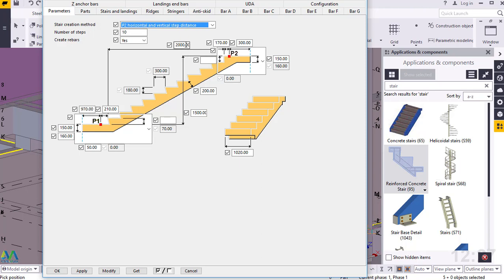I'll be feeding 2 meters here, and the height of our staircase, taking into account the full height of the ceiling right from the finished floor level, is 3 meters, and I took half of that dimension. Now I'm working with 1.5 meters. Now what we'll feed is just these two dimensions, 2 meters and 1.5 meters. The rest will adjust themselves to accommodate all these dimensions.